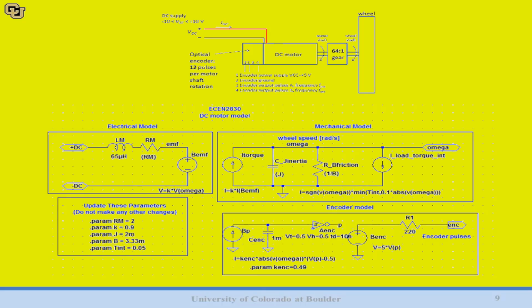And once we've figured that out, we can go back to our full model of the motor, and you can see we now know all the parameters in here. We know directly how VDC relates to motion on the gear shaft. And then additionally, we now know how motion on our gear shaft relates to our optical encoder. So we now know all the parameters to relate input voltage to the frequency read on our encoder.